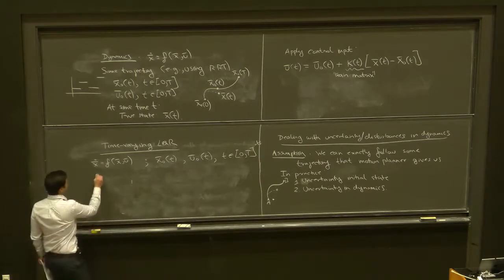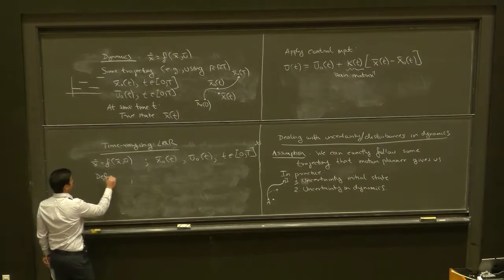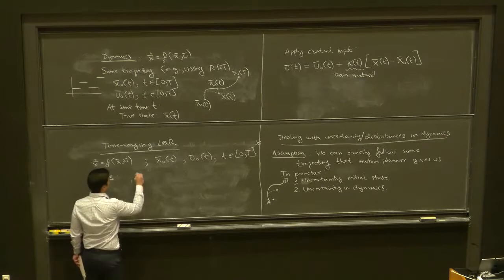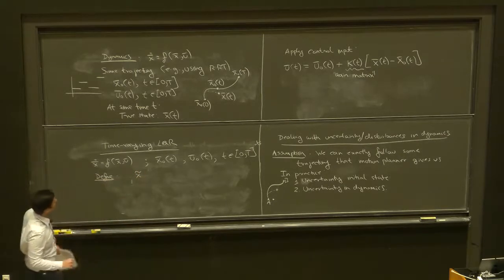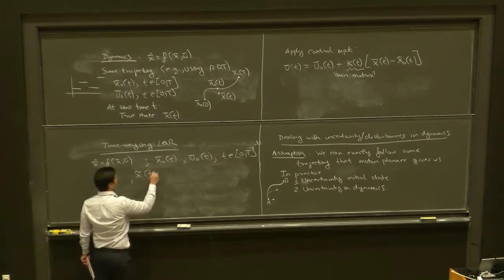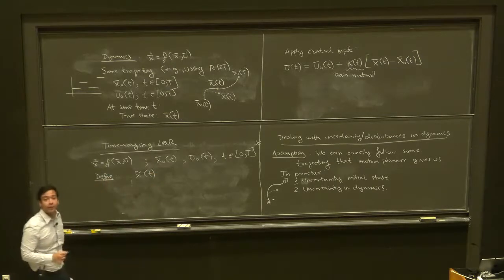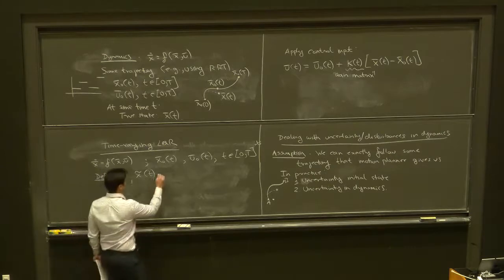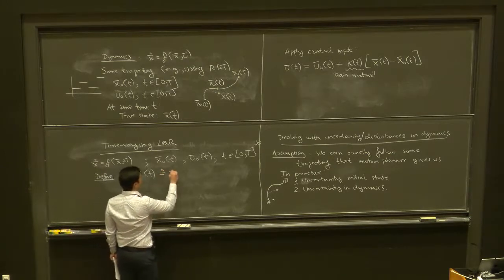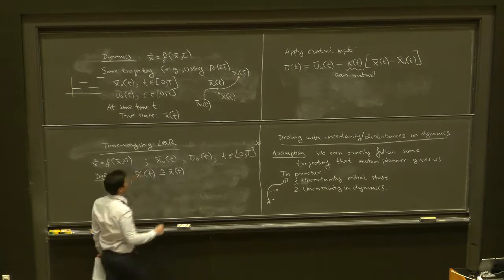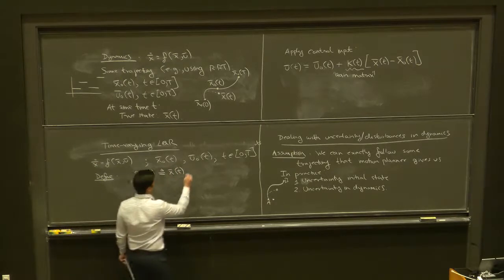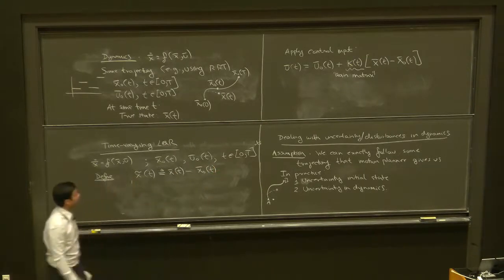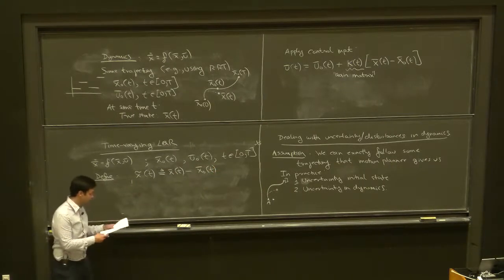We're going to define a new variable, which is similar to what we had done in our original LQR discussion. This variable x tilde of t is going to be the deviation of the actual state from the desired state. So we're just going to define this to be x of t, the state that your robot is actually in at time t, minus the state that you want to be in at time t, so the nominal state.